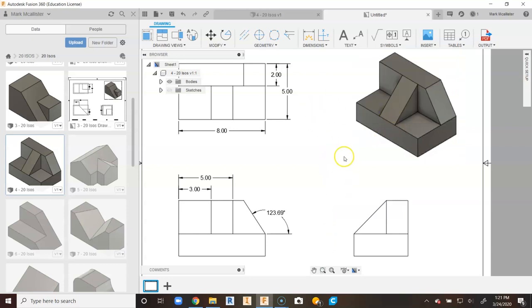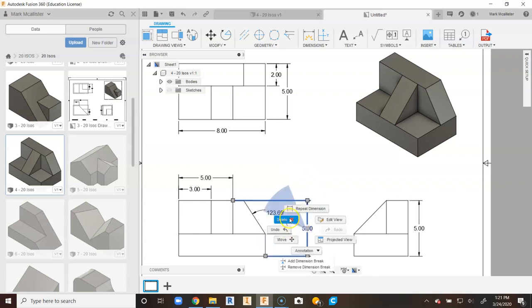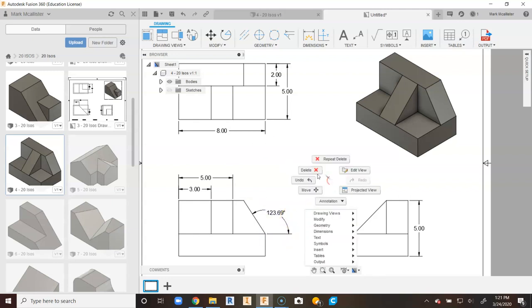So I'm going to place my full height dimension to the right of my side view. I'm going to place it over here. Now this is technically non-adjacent, but I'm going to say I otherwise could not avoid it. I don't really want to place it in my front view, going from like here to here, because I don't want to leave this kind of on the inside. I know that people would be able to see that and they could say, that's easy enough to understand, but I choose to keep mine between the views and try to avoid any confusion or overlap.